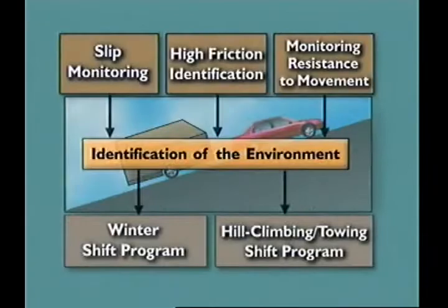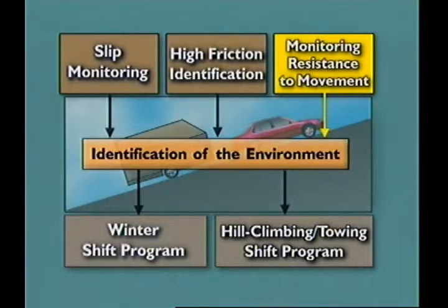For driving on steep gradients or with a heavy load, a performance-type shift program can prevent hunting or too frequent up and down shifts between adjacent ratios.